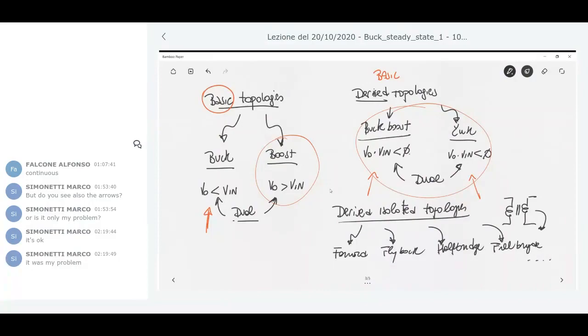The linear voltage regulator cannot include within its architecture a transformer, and you have to put it on the external side, but this transformer can be very heavy, etc. The transformer here can be very small, because typically this transformer will be operated at the switching frequency. Okay, and the switching frequency is in the range of hundreds of kilohertz, something that I already mentioned in the first slide. So these are our basic topologies.